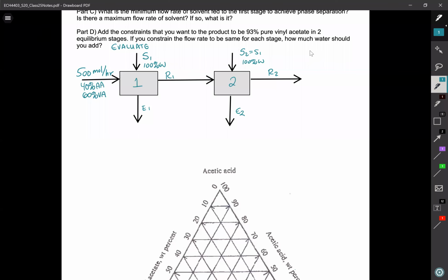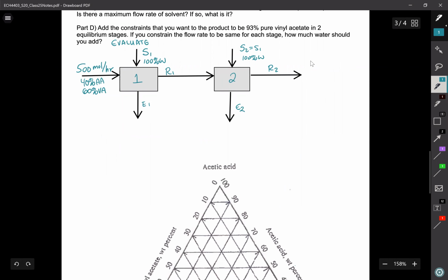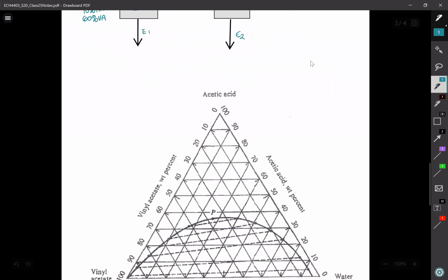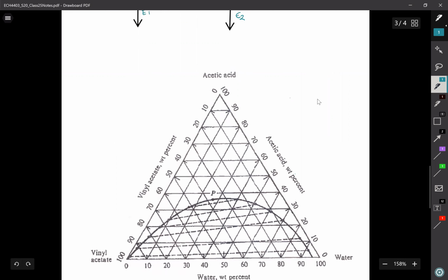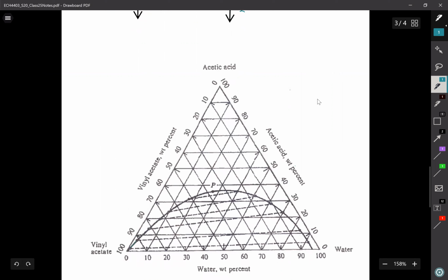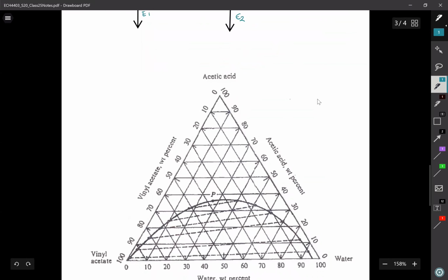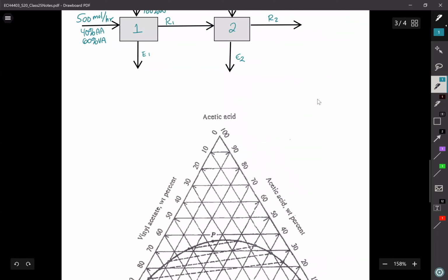So what are we going to do? So it's a guess and check problem. I have to make some initial guess in order to evaluate. And unfortunately, because I'm solving this graphically, I can't really goal seek in Excel. So the textbook, Lane, kind of goes through some ways that you can solve this in Excel. His way involves figuring out a fit for this data, fit for the equilibrium data. I think that's a little bit too much detail that I want to go into now, especially considering that we are online. So we're going to do just the graphical approach.